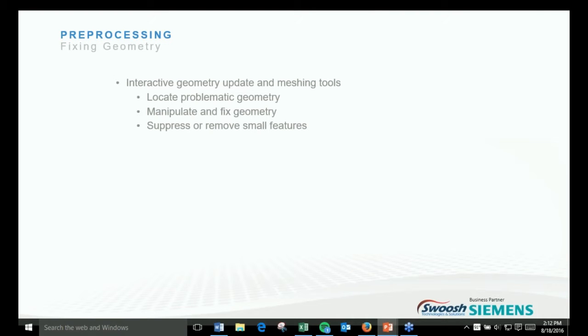So let's talk a little more about fixing geometry. I talked earlier about locating some slivers and curves and things like that. These are troublesome things that we all have to deal with when solving. Short edges and gaps: one of the main challenges to be overcome is the creation of a finite element model. Sliver surfaces lead to badly shaped elements, as I said before, and finding them really becomes problematic. Just seeing where they reside can be a major task.